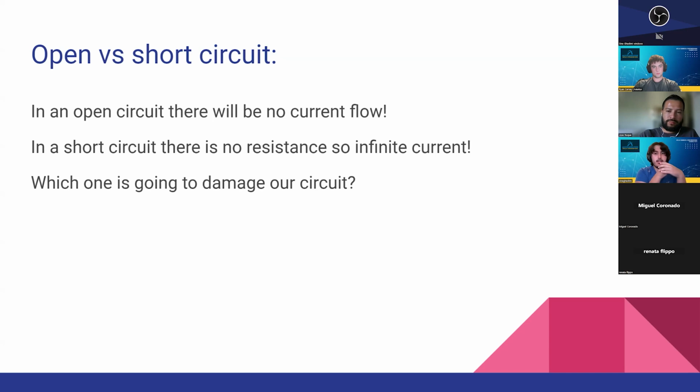Later on in industry or in your classes, you'll see that it's really important to design a fuse that actually works, not one that's just there. Sometimes you need a mechanical aspect for your fuse to push away or pull away the higher voltage side, so you never conduct current again until your device is fixed, because you want to protect your circuit. Any questions? Nobody has any questions?